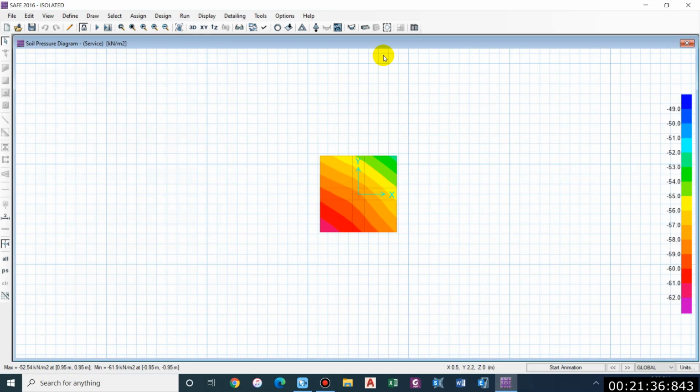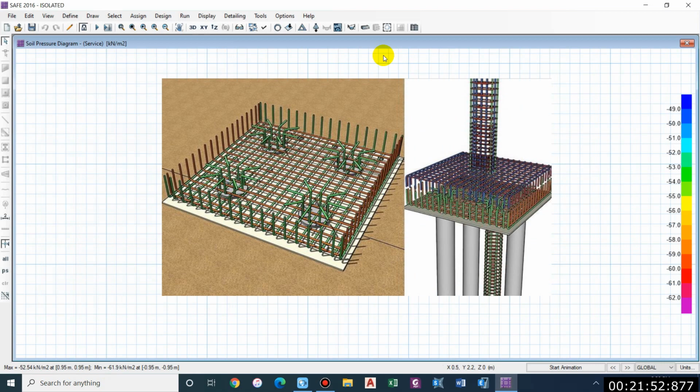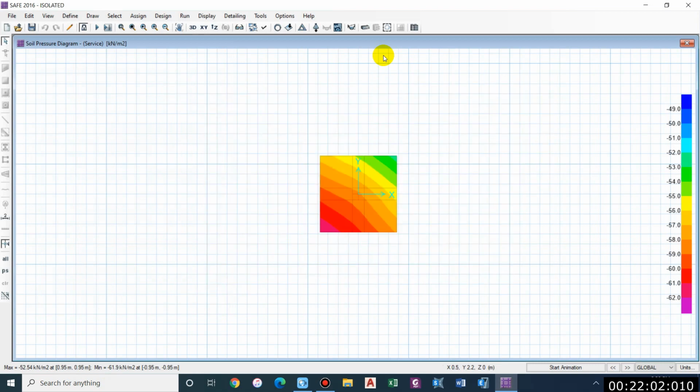If the swell bearing pressure exceeds the allowable value, then we have to go for a greater size of foundation. But in case of poor soil condition, where the bearing capacity of the soil is very less, such as sand, then we have to go for deep foundation such as pile foundation. This pile supports the structure by the skin friction between the pile surface and the surrounding soil and end bearing force, if such resistance is available to provide the bearing force, and accordingly they are designated as frictional or end bearing piles. Now let us check whether the depth of footing is sufficient for the punching shear or not.